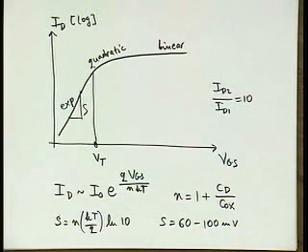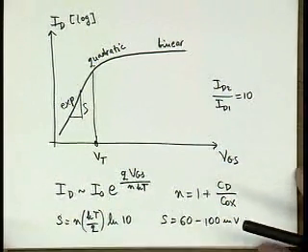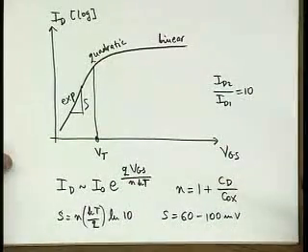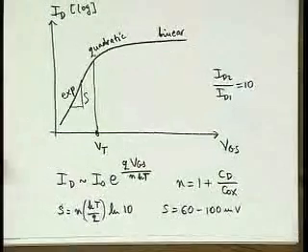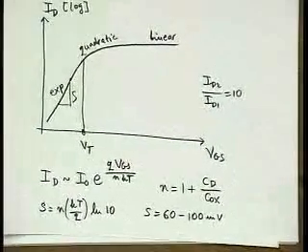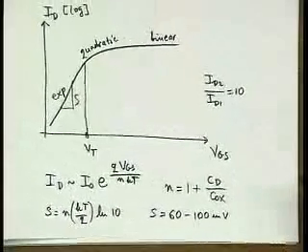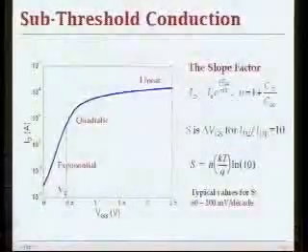Yes? What is CD? What is capacitance CD? That's drain junction capacitance. We'll see that in more detail in the upcoming lectures. But this is a really important effect in modern designs, and it's quite scary that you have an exponential increase with the scaling of thresholds. Okay, and we'll get back to that in the analysis of power consumption. Now going back to slides.